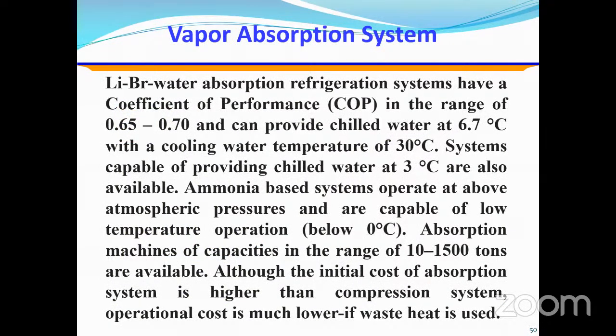Lithium bromide water absorption refrigeration systems have a coefficient of performance, that is COP, in the range of 0.65 to 0.70 and can provide chilled water at 6.7 degrees with a cooling water temperature of 30 degrees.